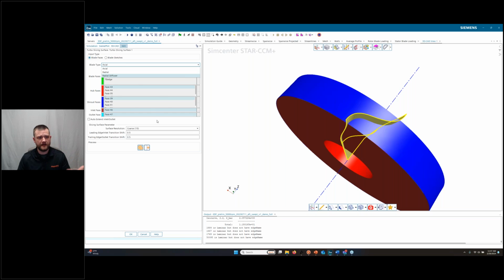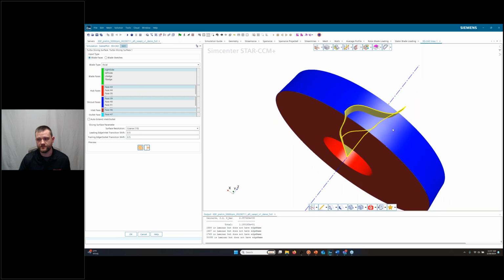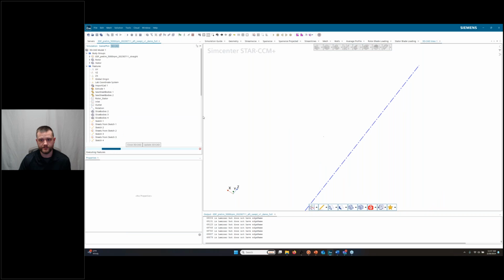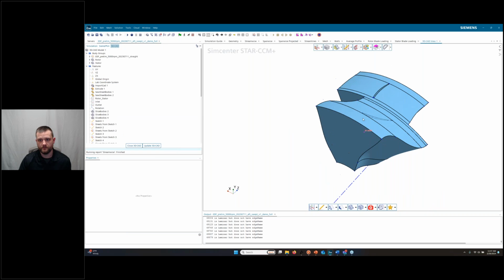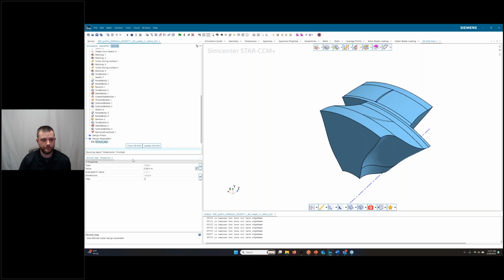We also have a few tools here to change how sensitive this surface is depending on the shape of your turbomachinery geometry. So it makes it really easy to create these nice, clean, periodic regions. And this is what I would have going into Star for my geometry. I've also, in this CAD geometry, parameterized my shroud gap.